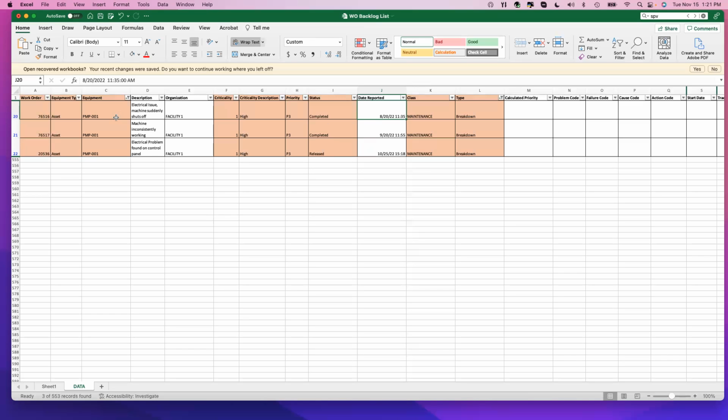If it's repetitive, then creating a PM would be beneficial for the company, as we want to make sure that this critical asset is operating efficiently, operating most of the time under normal operations. We want our equipment to be available, because if not, we're going to be on downtime, and that's going to affect us.